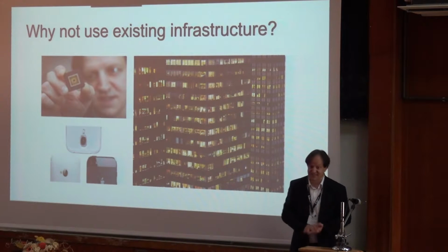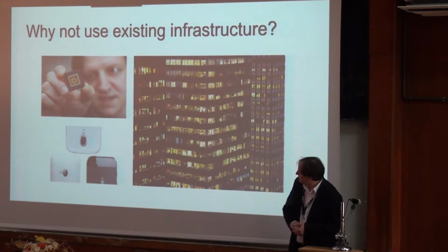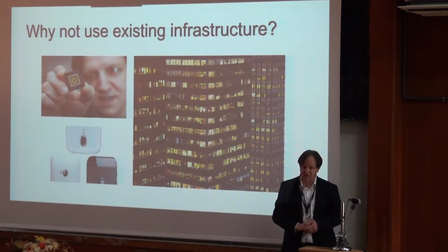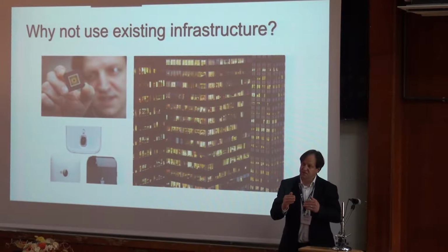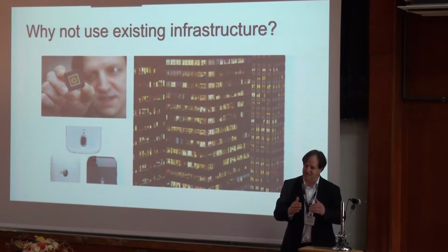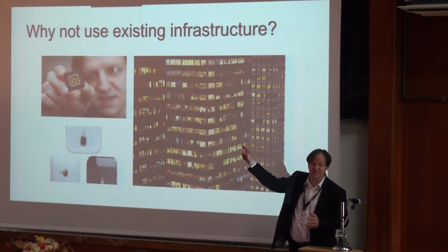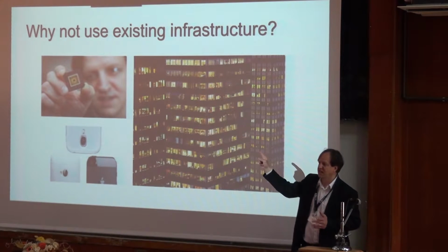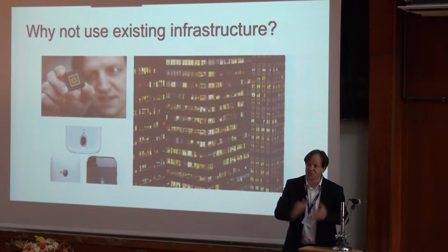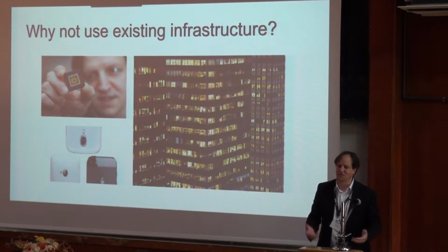What we need is little devices. We have a chip there on the left side corner, which is a 2.8 by 2.8 millimeter die on CMOS that houses 49 detectors. So what you have there in 2.8 by 2.8 millimeters is a massive MIMO receiver.